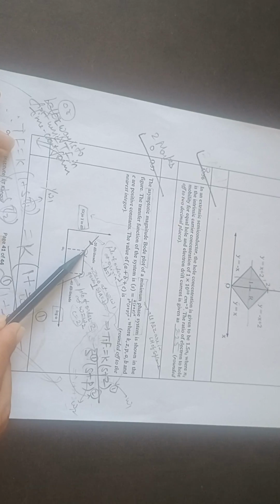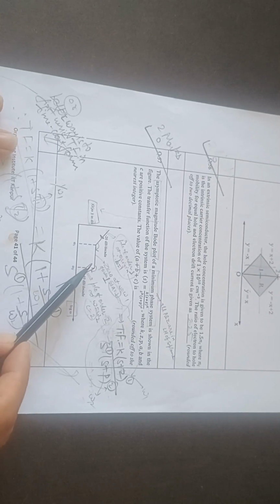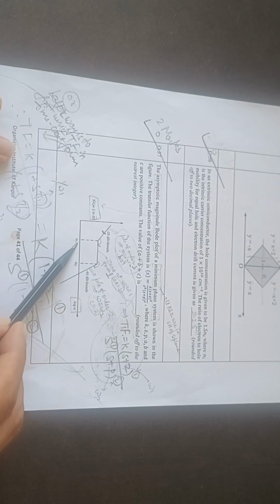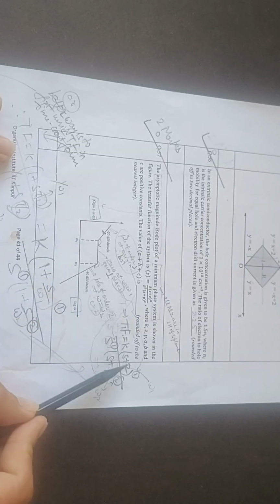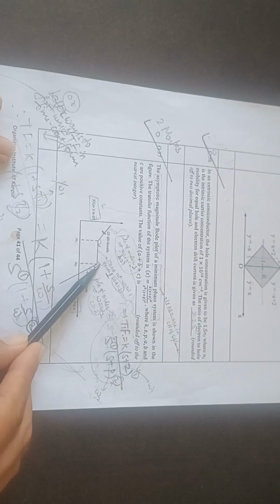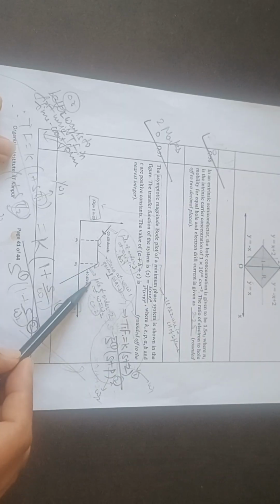Then the slope changes to 0 dB, which means there is a zero at omega equal to omega 1, of order 1. Then again at omega 2 the slope changes to minus 40 dB per decade, so there is a pole of order 2 at omega 2.